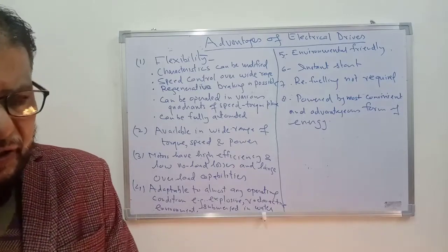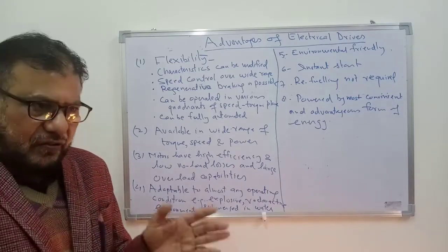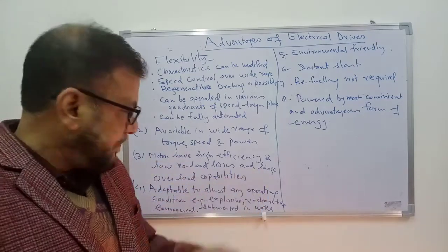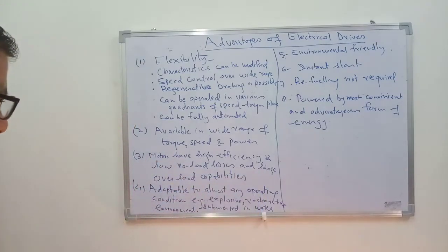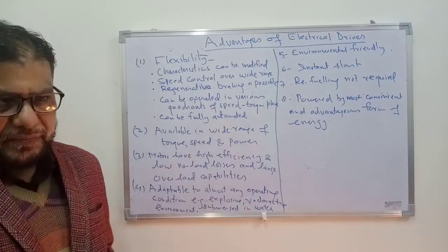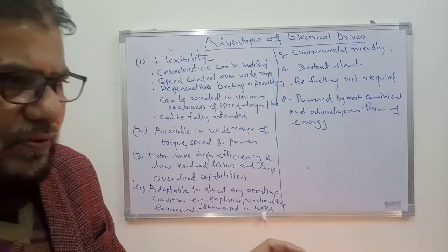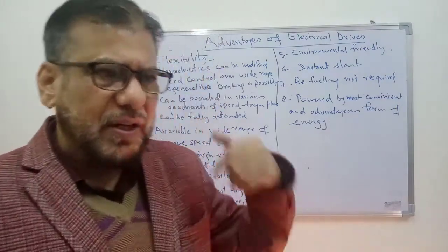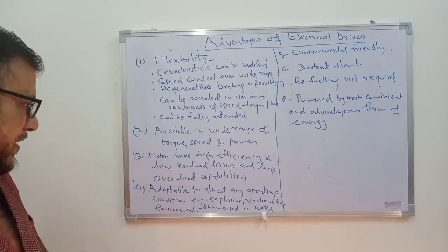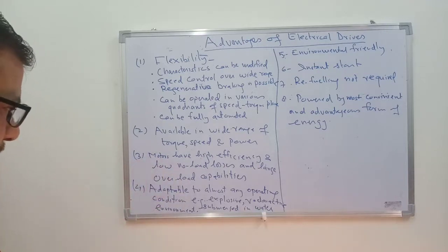Even if you don't connect any load, 50% power is wasted. In this case, the no load losses are not high. And they can be overloaded very easily. For a short interval of time, you can overload the motor for double or triple the motor rating. So this is also possible in the case of electrical drives.